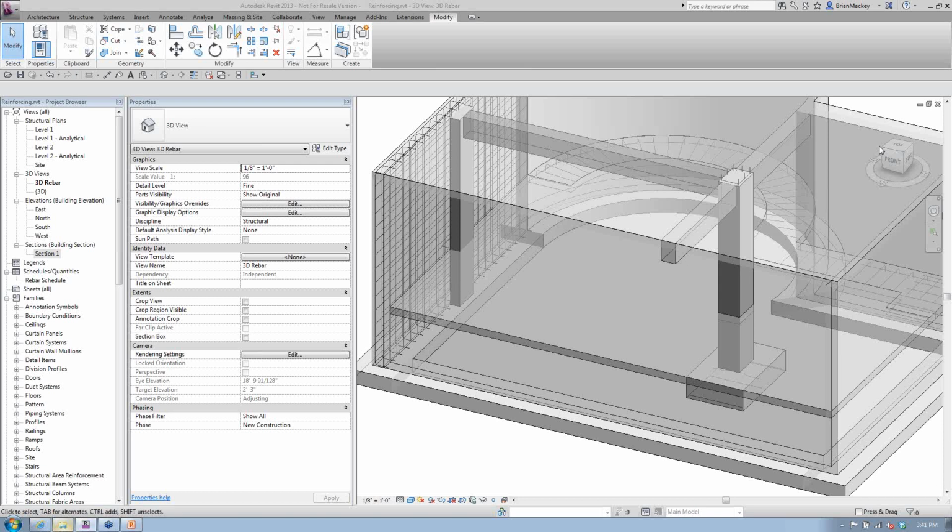Wall. So you would just go place a single bar up at the top, and you can do it in either direction. Again, it's going to get placed where you're at. A lot of times I'll just go into a section because I can place it a little bit easier when I do it in a section. So if I just want to place a rebar inside of a section, I can go grab my rebar. You can change your shape out if you want to. Just go to a 0. Am I doing it parallel to the work plane?